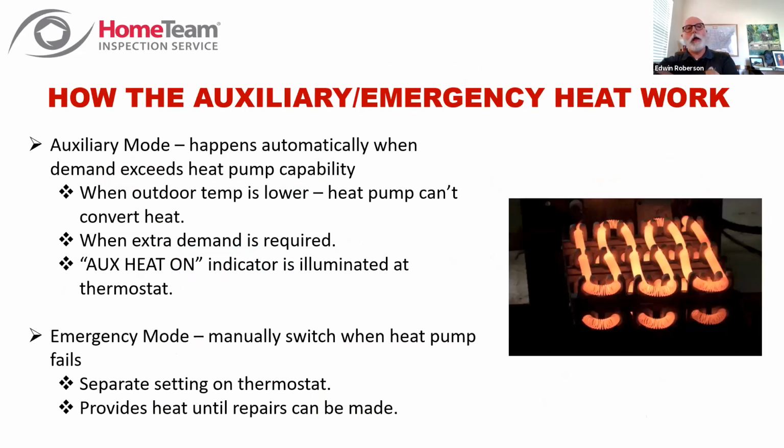So in that heat pump, we are in a zone of the country where if you get much further north from us, you don't see heat pumps anymore, because the weather's too cold, there's not enough heat in the outdoor air for conversion. And heat is a relative term compared to what the refrigerant can do. So down to about 30 degrees, there's enough heat in the outdoor air still for that refrigerant to do its job as it's going through that cycle.